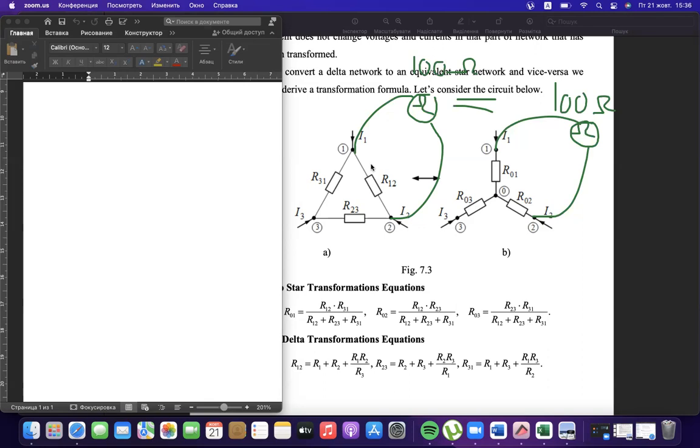It puts some small voltage to make some small current and measures the resistance of the object. If this triangle or this star is disconnected in the circuit, just some combination of resistors that, for example, lie on the table without any electrical connection, that is what you will get. This ohmmeter will measure R12 parallel to the serial connection of R31 and R23.